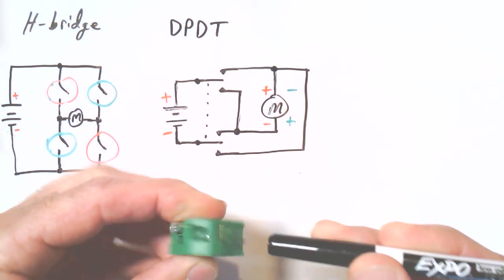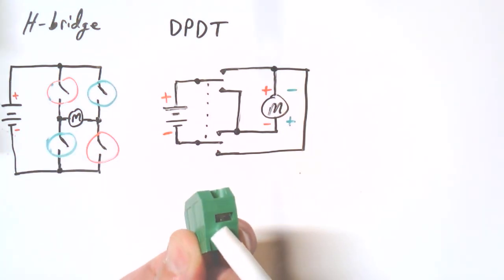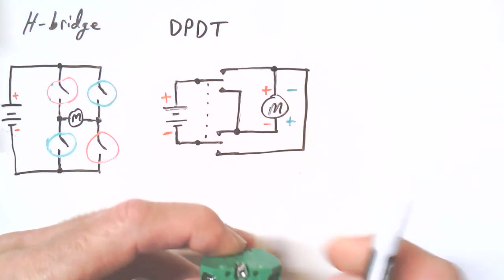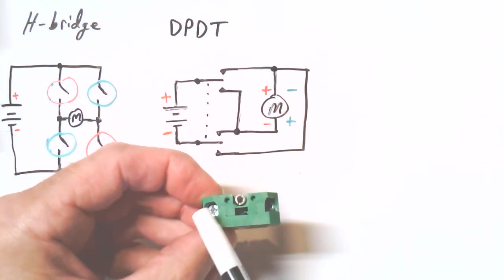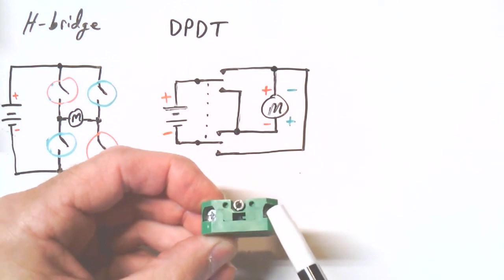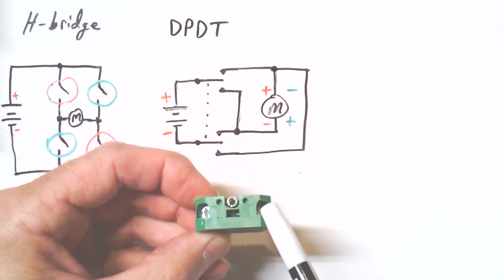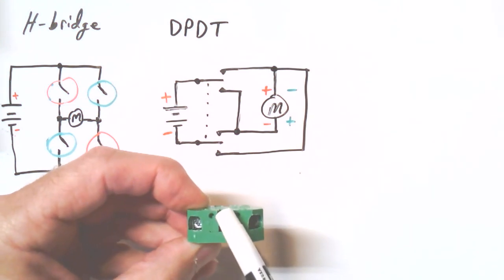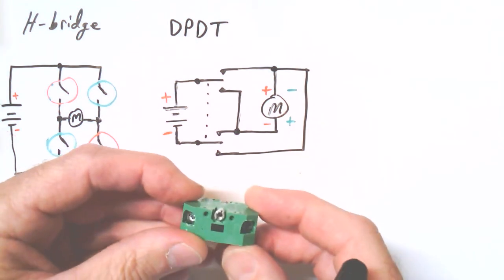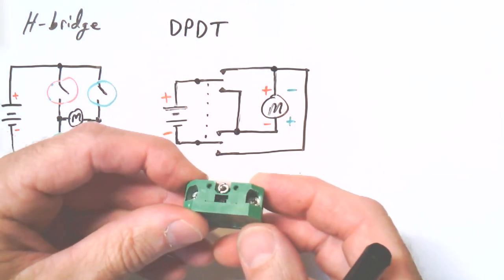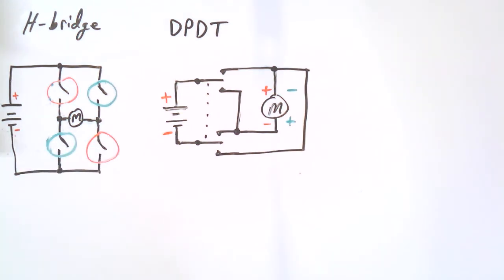And when that pushes in, then the two terminals, which we see one on this side, one on this side, or right down the front, you can see the screws that you would turn. Right there is where you attach wires. This is a normally open contact that will connect this point to this point. This screw is to actually do the physical mounting of the contact onto the actuator. So we'll show you all that in another video. I just wanted to bring it into this video.